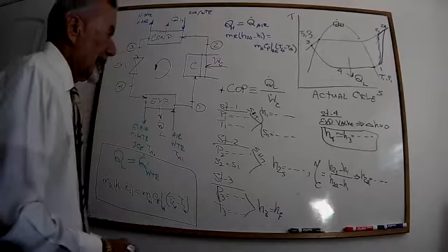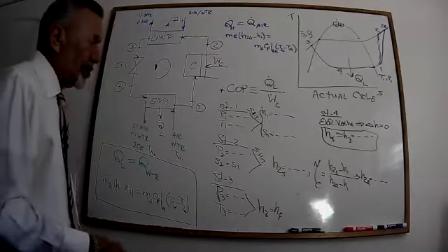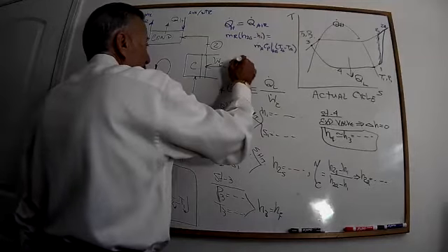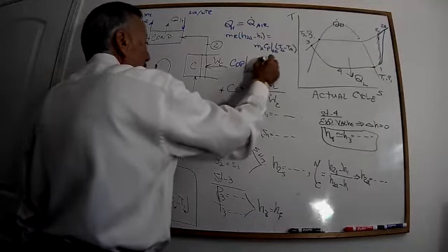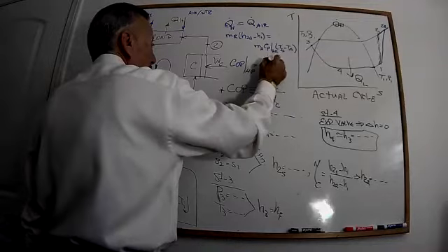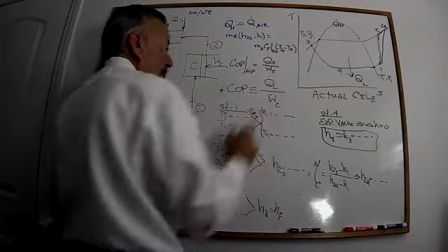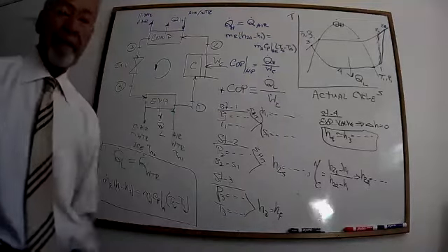Yeah, so your product is the outgoing hot air or water in that situation. Right. So the COP of a heat pump is equal to the QH divided by the work of the compressor, the opposite of that, because in a heat pump, that's what we're looking at.